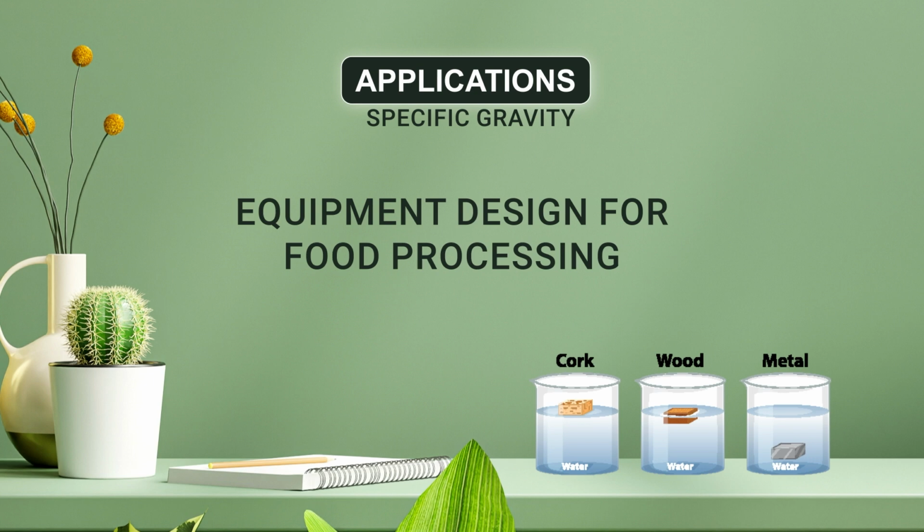Look at the figure at the bottom. One particular substance is settled at the bottom. The second one in the middle is completely floating. And the third, the last you see, is half floating, half sinking. I'll give you the example of a material with specific gravity 0.8. Suppose there is a solid material of specific gravity 0.8. If you put it in water, 80% of it will sink, 20% of it will float. If the specific gravity is 1, it will not be sinking, it will not be floating, it will be at the same level. But if it is, say, 1.2, the whole material will sink.